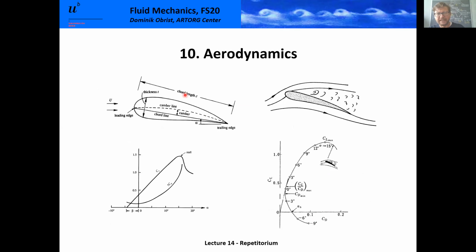We also looked at a little bit of wing theory. We introduced a bit of the nomenclature and terminology in wing theory. We looked at a certain family called the Joukowsky airfoils, which can be applied to potential flow theory. We looked at what's happening in stall, where a separation point is very early. We have separated flow and usually turbulent recirculation zone. And we saw what this means in terms of lift coefficient, drag coefficient, and how we can plot this into